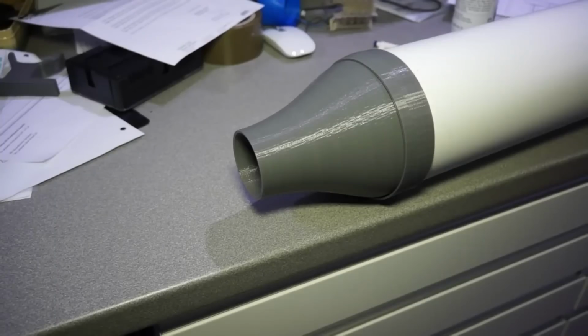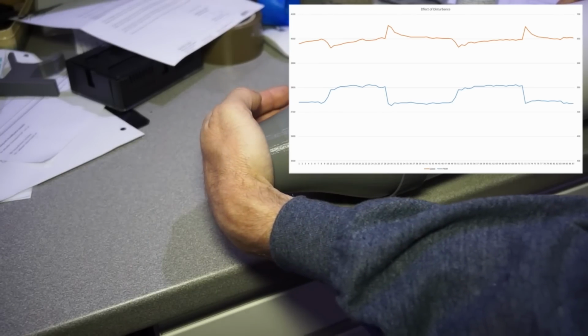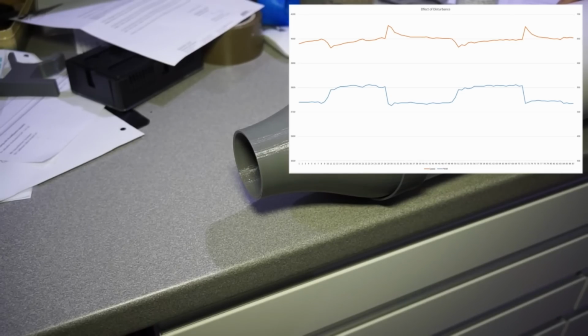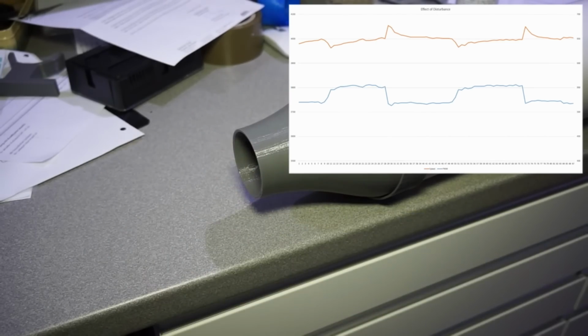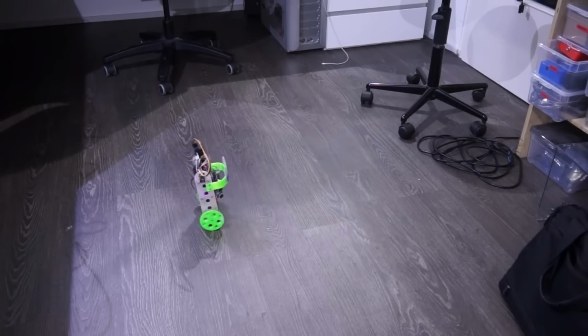But after all the work, let's check the results of the wind tunnel. If I block now the exhaust, the RPM stays stable because the PI controller automatically adjusts the PWM signal. Job done. I hope it became clear on how these controllers work, and also that finding the right combination of P and I factors is a try and error process.